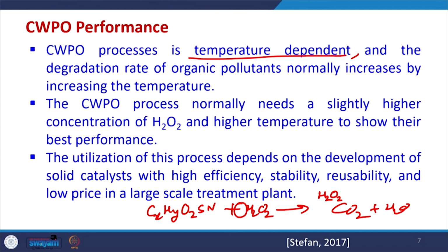So, we test with respect to the stoichiometric H2O2 requirement what the actual H2O2 requirement is. This optimization can be done by performing lab scale studies. And after that we can use the usual catalytic reactor design approach for using the catalyst for wastewater treatment.